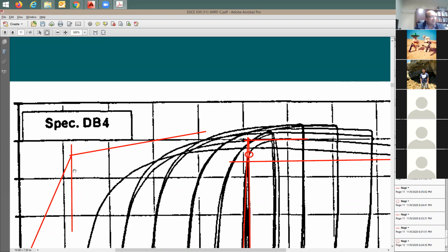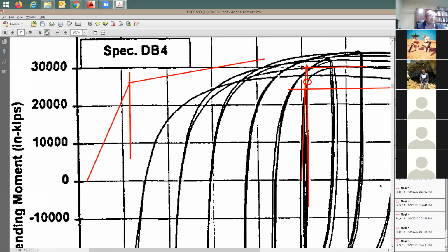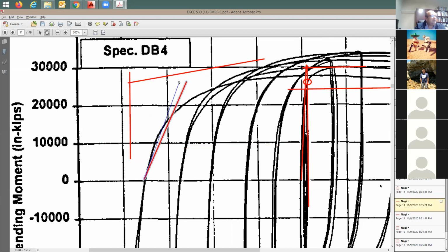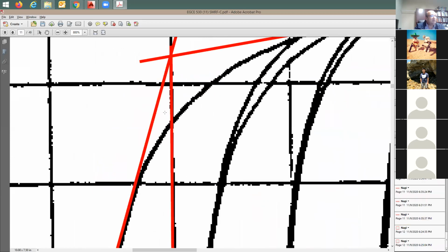And once it hits the curve, you're gonna see now this gives you the point. Let's say that this is one of the tests, one of these values. And let's say that this gives you the 0 point, because actually I don't have a clear one here. So I'm gonna say here's the first tangent. You can just take this line and fix the slope. Maybe this is a clear section of the picture. It gives you the second one, right? And then once they meet, you say, okay, this gives you the point. And the actual yield point in terms of force and displacement is this one here.